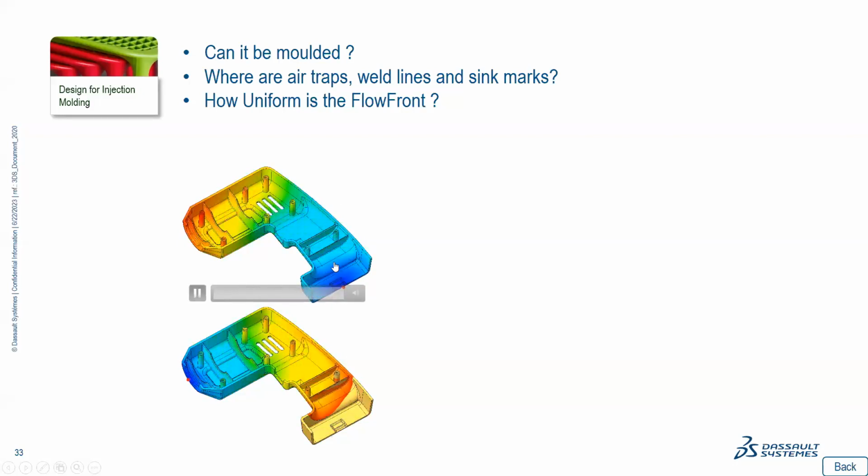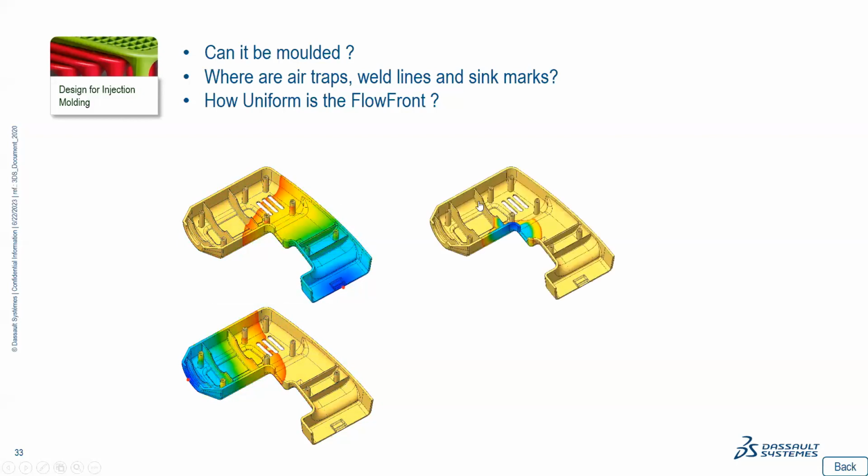So maybe in reality, the best way to inject this plastic part is having an injection point at the middle. So then you will decrease the pressure of injection. So here you can see maybe here's the best location to inject.